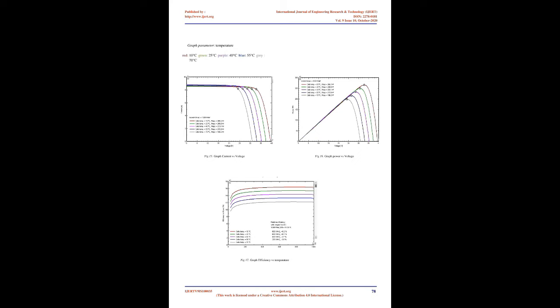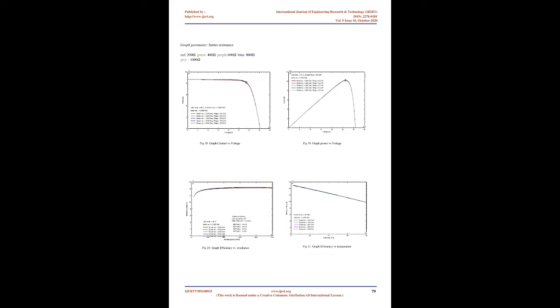These parameters therefore include GREF and TREF, the reference irradiation and module temperature conditions during reference measurements, usually standard test conditions STC; ISC and VOC, module short circuit current and open circuit voltage at these given conditions; IMPP and VMPP, any operating point in the region of the maximum power point, at these given conditions; μISC, temperature coefficient for ISC.